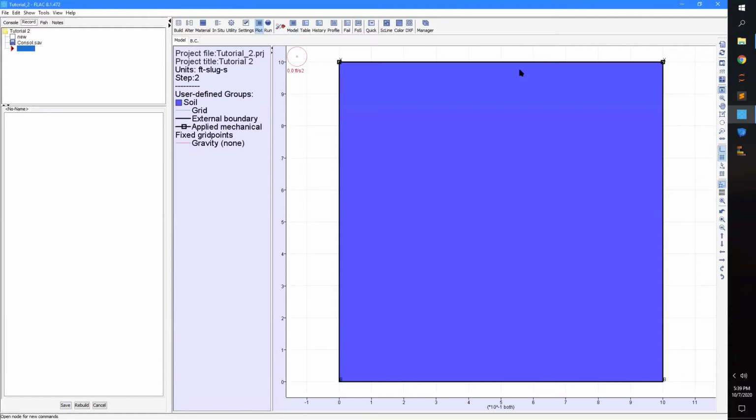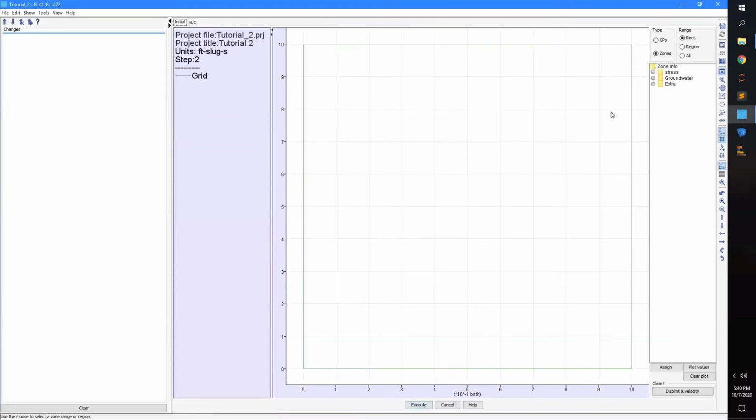And so one choice would be, if we remember that we had a shear strain at yield of 4.635 e to the minus 4, we could pick the number of steps such that we get it just to yield. So let's do that at this particular time. But we will continue to increase the shear strain until past yield, until it reaches that maximum, like in the picture that I had included in the lecture notes. So let's initialize in situ and initial, okay?